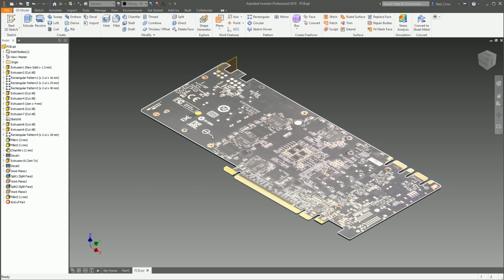board in. What if you wanted to change the revision on this PCB board and cut a hole through it? You'd have to then do the same thing on 200 parts that you've put this into. So to avoid that, you'd derive it into the parts and you'd get that live link. You make a change to this, and anywhere it's been derived into, those will update. So let's see that happening.